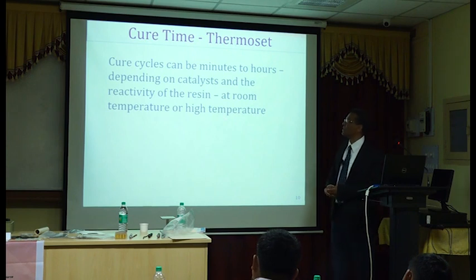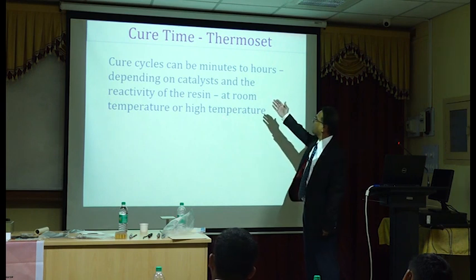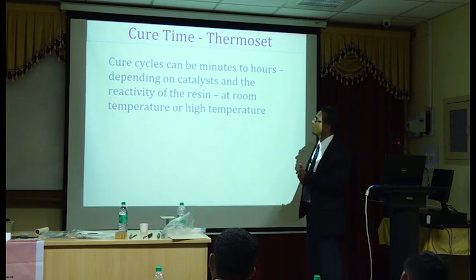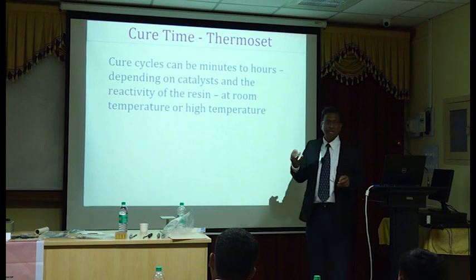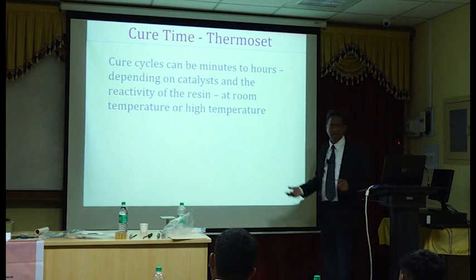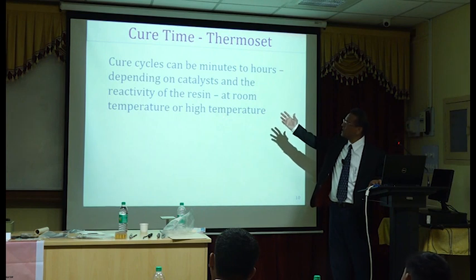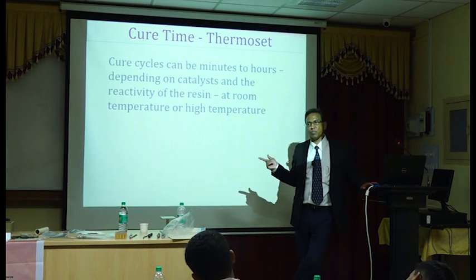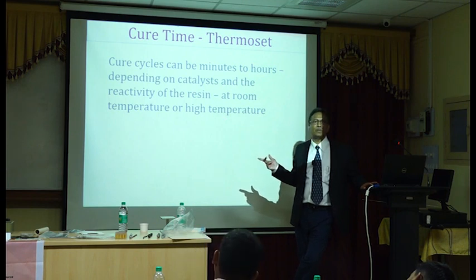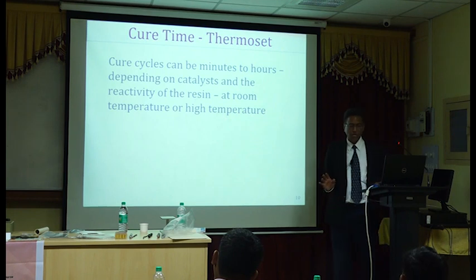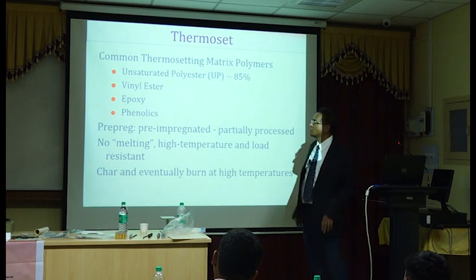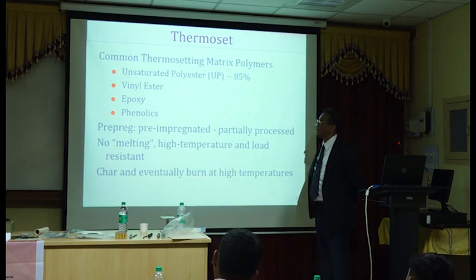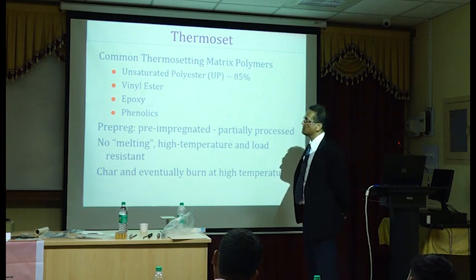So curing time again depends on what you are using. It can be accelerated curing method. It can be reduced or prolonged curing method. You can apply heat to accelerate the curing process. So everything you do with your curing is dependent on the chemistry of the product. So you should never hesitate to ask questions to the supplier. You say, what should I do? They should have an answer. Okay? So for everything, you should consult your supplier, make sure you use the right process, right temperature. Everything is important in everything actually. Even in reinforced concrete construction, we have to make sure everything is done to the specifications.